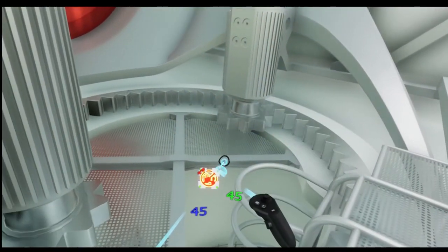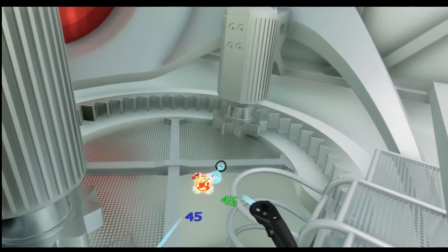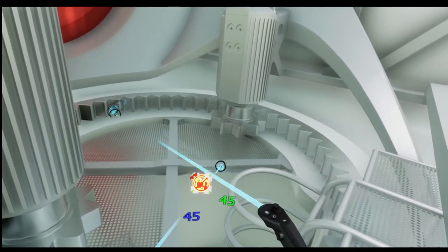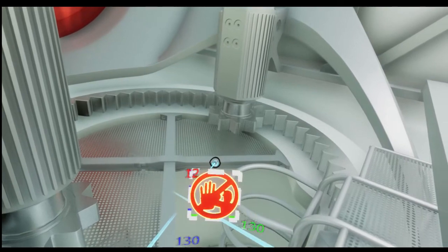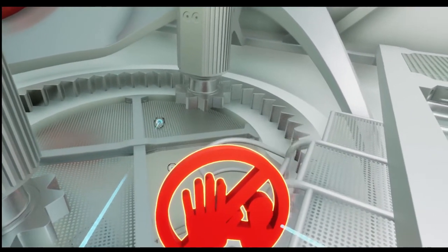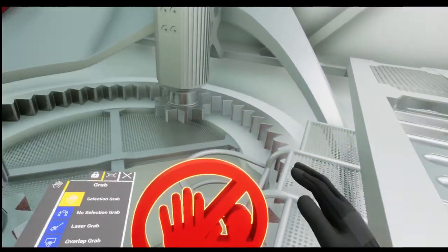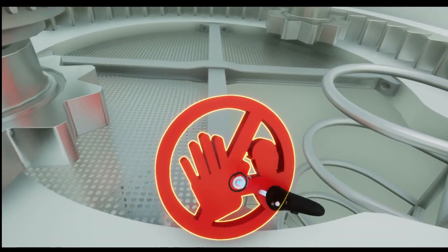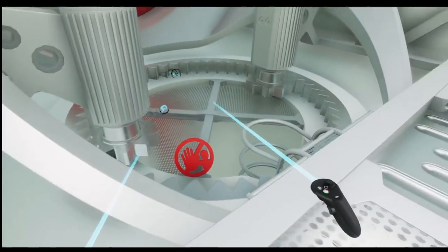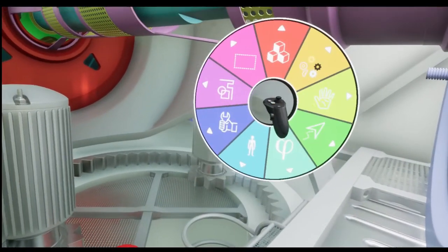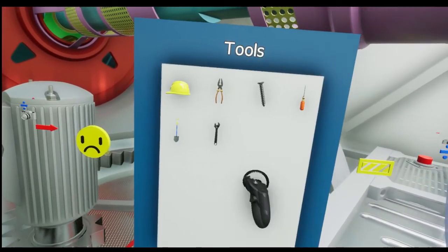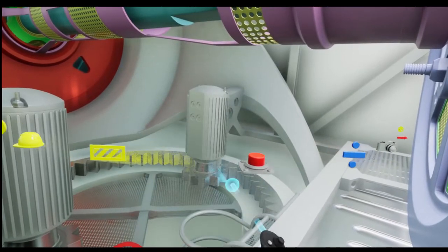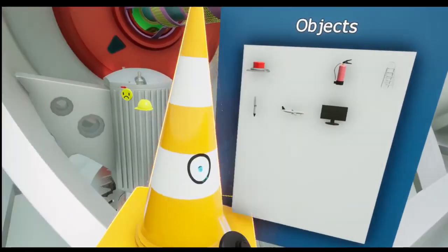Now, while Nicholas is doing this, I want you to notice that there's a large geared system on the ground there. So not only is there a falls risk there, there's a crushing risk, a mechanical crushing risk. Now, normally these things would be locked in place while maintenance was occurring, but failures do occur. So we need to make sure that people keep their hands clear of that area. Nicholas, could you show us the cones that we can use to cone off areas?